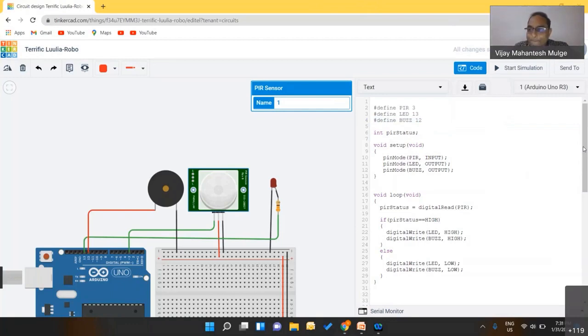Yeah, there is a question: can I add one more buzzer? Okay, so you can use as many buzzers as possible, because you just need to understand the capability of a particular controller, how many devices it can support. Now, if you look at this case, there are so many empty pins available, right? You can connect one LED, two LEDs, three LEDs, and so on. Similarly, you can connect any number of buzzers here. If I have to give you a simple example here, assume there are two.